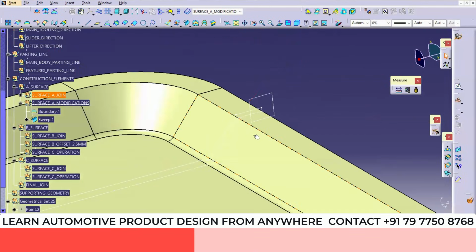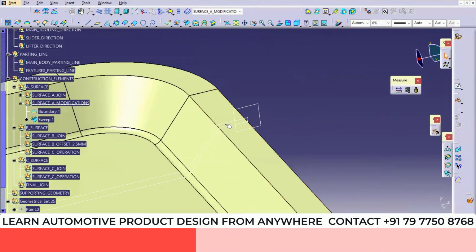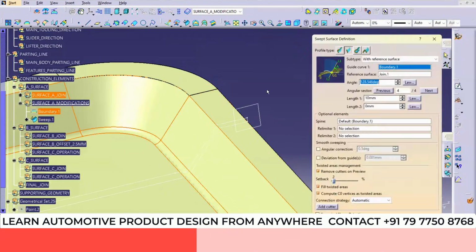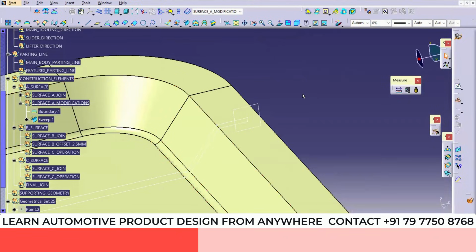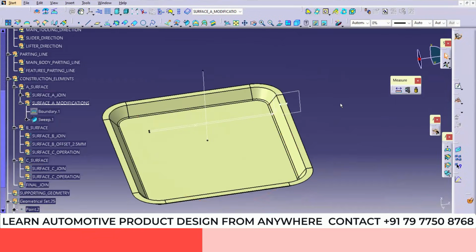So if you use the extract command and then create the surface, the problem is that in future, if I want to change the length of this, I can change it with the sweep: if I want 15 mm, I just change the value and it automatically changes. But with the extract command it's not possible to change the value, because extract is a dumb element, right? That's why extract is not allowed. We want everything editable.